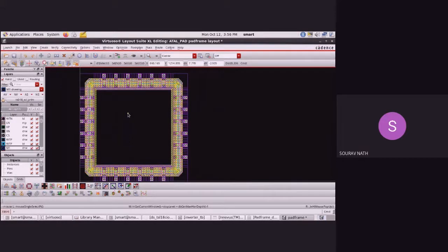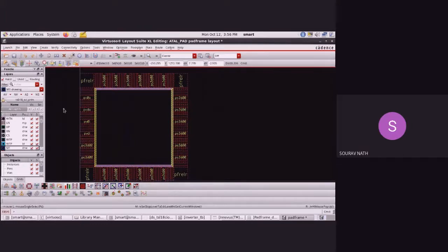First of all, before acquiring, you have to verify which is the power pad and which is the ground pad. Everything should be identified. So for that, Control F and check the name. PB0A, PBDA, these are the IO pad power pad, and these are PB0I and PBDI, the power pad of the core circuit. So I have to make sure that I have connected the power rail VDD and ground to this IO pad. So first of all, let's connect this one.